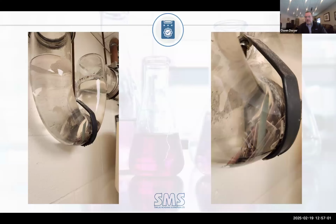This is a very typical college lab, and luckily it was glass piping, and we were able to see what was being intercepted in the P-trap upstream. They didn't have an interceptor. So their tank was getting plugged, and in the next room, you could see why. It's broken glass and pipette tips that end up down the sink.